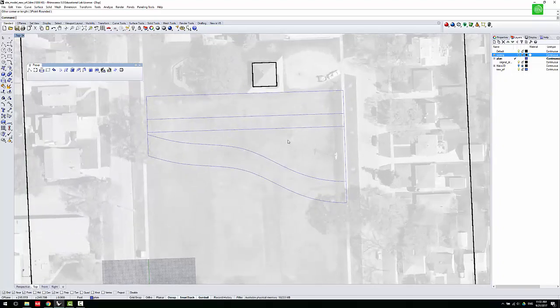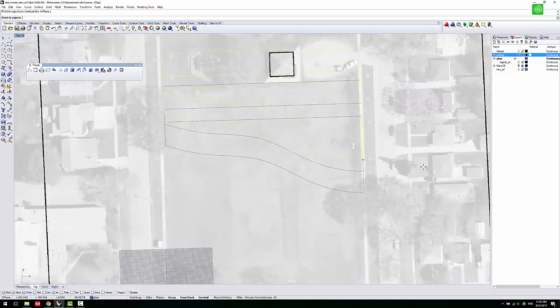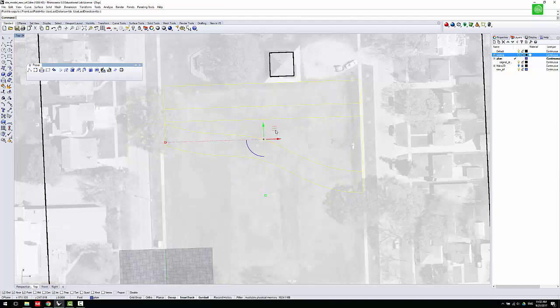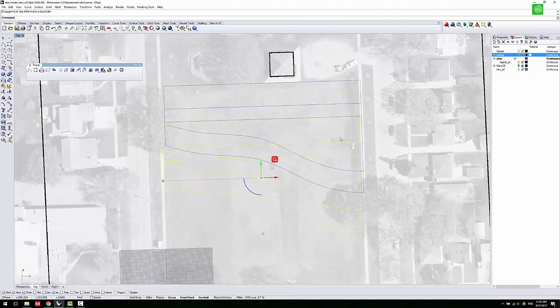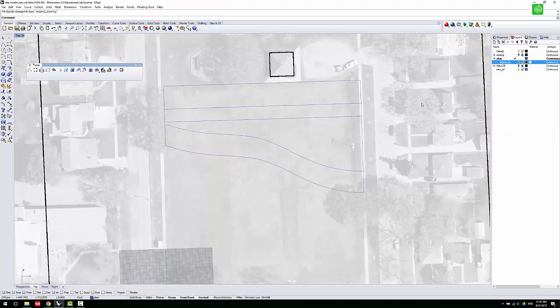Once you have this, what I usually do is copy over the lines. Once I copy, I hover over out, see here, and then I go back. These are the lines, and there are two pieces. Once it's copied, I right click this layer and change object layer, which means if I hide it, all these lines are in the plan view. If I change this, I don't have anything here, but I still have a copy of it in here.